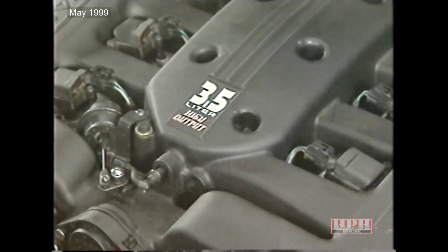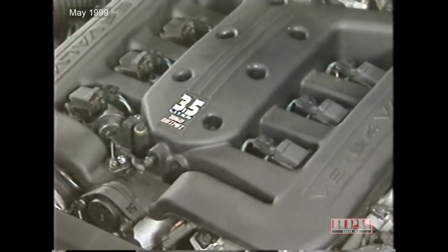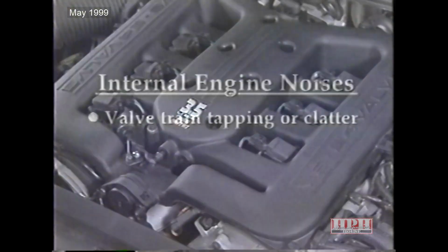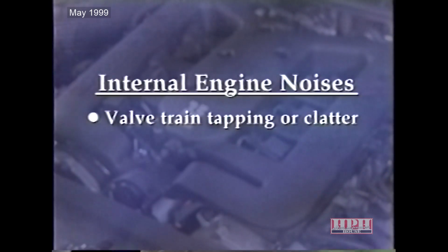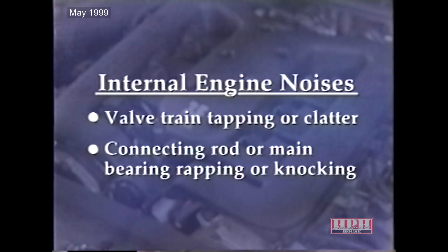If a vehicle is operated for long with low engine oil levels, you'll probably begin to hear noises from inside the engine. You may hear a tapping or a clatter coming from the valve train. Sometimes low oil will result in connecting rod or main bearing rapping or knocking.